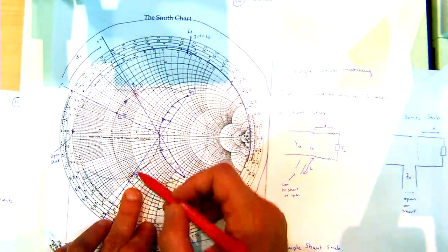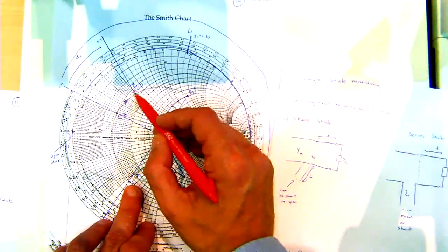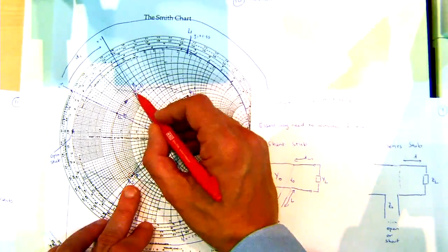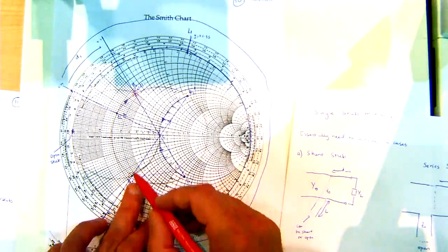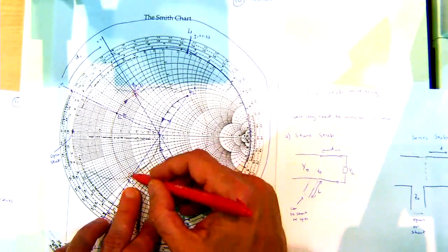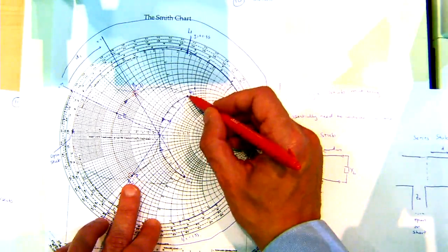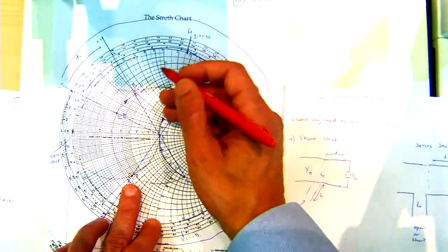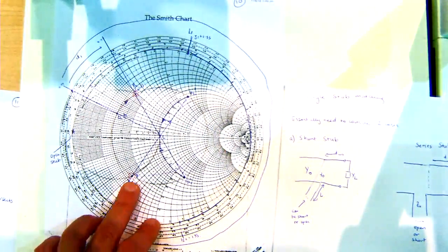This is just an impedance that we've added, which also tells us that essentially we've got a length of line this much or a length of line this much, which will get us to a location where, when we convert to admittance, we can add a complex bit and it will cancel out and we'll get a perfect match.